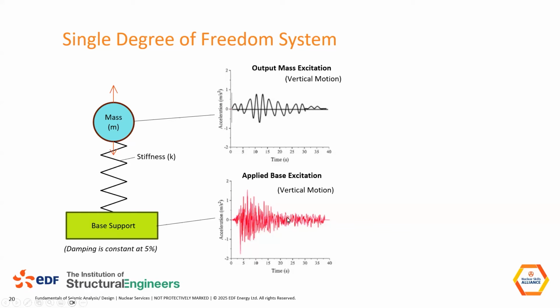And basically what happens is, like I said, we shake this bottom part vertically only. The mass moves, or has again, displacement, velocity, acceleration. Let's say acceleration accelerates with a different response, and we measure that. And that is our system for generating a response spectra.